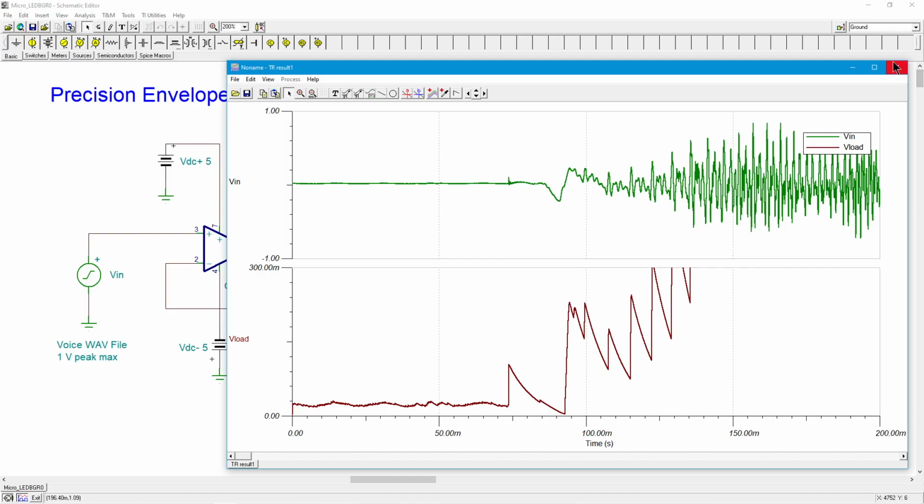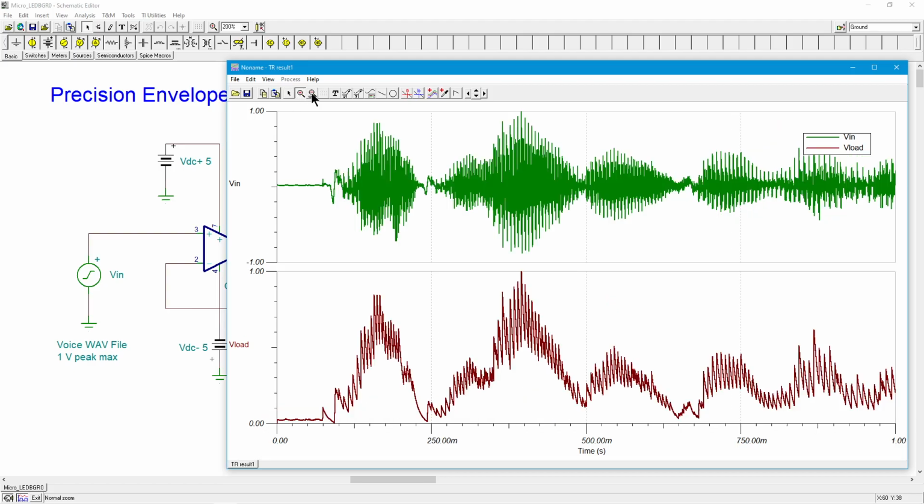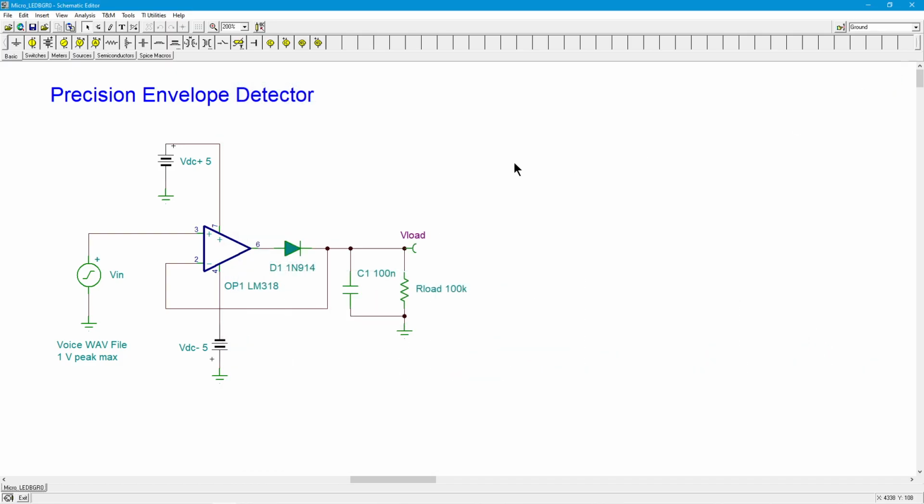So if we had a larger cap, that would make it a little bit more full. You wouldn't see quite so much, I guess I'll just call it ripple, right? It would track this a little bit more closely, but that's just something you have to play with, right? You know, what's going to work in your particular application. All right. So we've got code, we've got an input circuit. Bingo, we've got ourselves a microcontroller version of our LED display, bar graph, dot graph, whatever you want to call it. And like I said, this version, a little bit more complicated, but definitely more flexible.